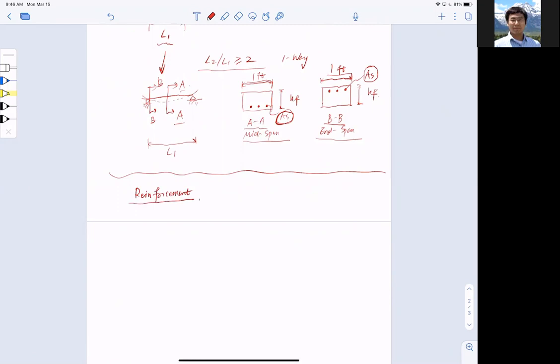So we have to come up with an equivalent reinforcement concept, that is AS per foot, equal to AB, which is the provided reinforcement area, AB here, multiplied by 12 inches per S, okay, so this is the spacing. All right, so we have to normalize it.